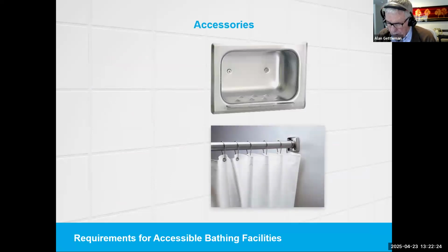Shower curtains work well as enclosures for users, including people who use wheelchairs. If other types of shower enclosures are used, they should fold back completely out of the way so as not to obstruct transfer to shower seats or interfere with shower controls. And they must not incorporate a track along the floor or rim of the bathtub.